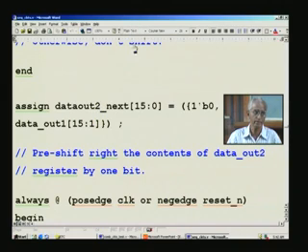When we simulate, we can easily compare the two and see that it is basically the same. And this is the concatenation of 0 for the MSB, that is the bit vacated, and the shifted part is on the right here. So 15 bits here plus 1 bit here, in total it makes 16 bits, that is precisely what is here.